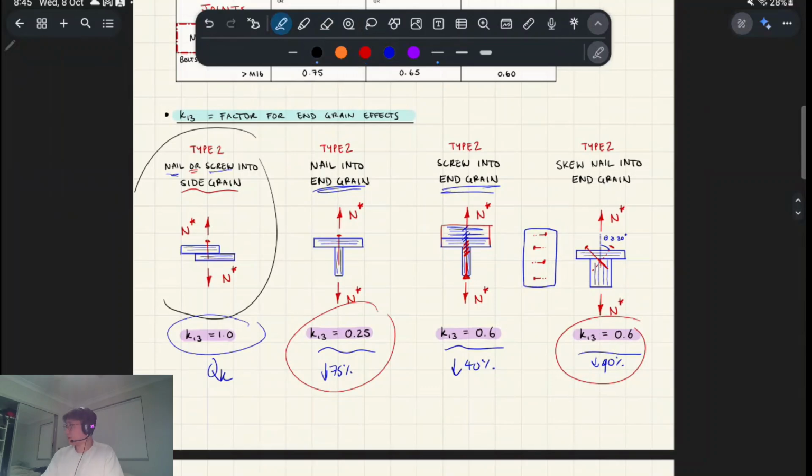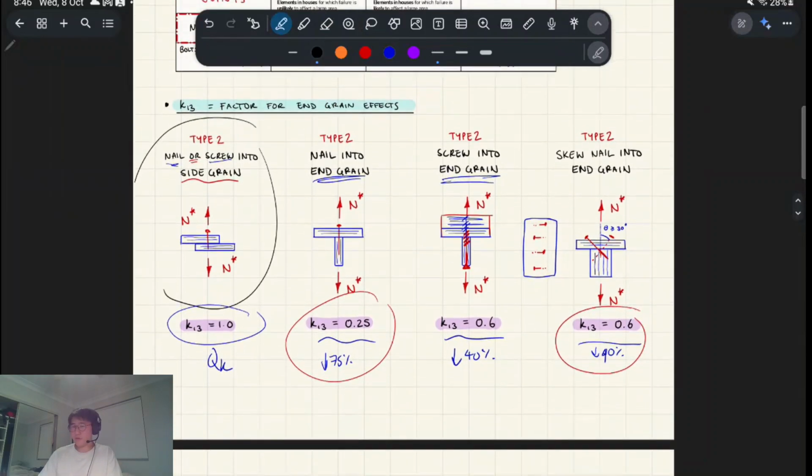Okay, cool. I'm gonna move on. I see Nathaniel typing here. Do you just use the nail gun on an angle for the skew nail? Yeah, that's right. You can. There are jigs for if you're doing something more precise, like woodworking. You can get jigs that can put connections like screws and nails at a specific angle. But if you're doing carpentry, it's a lot more rough, and speed's kind of the name of the game. So yeah, you just angle your nail gun.